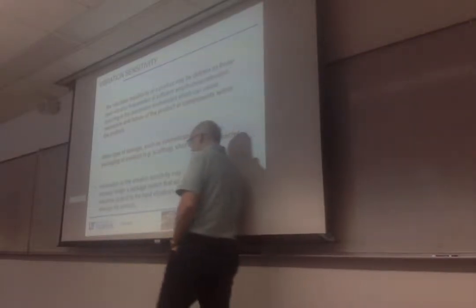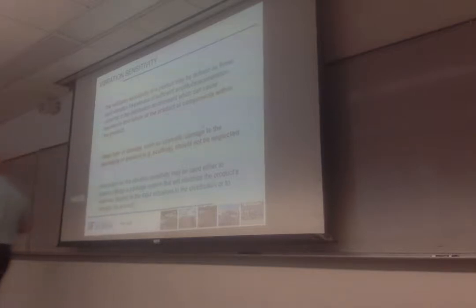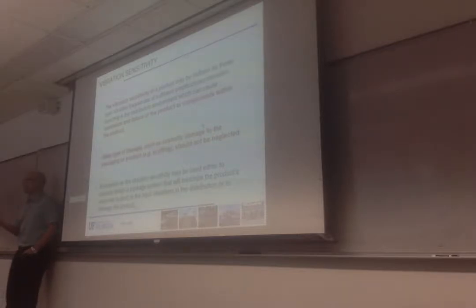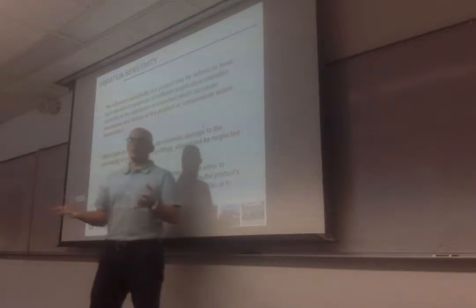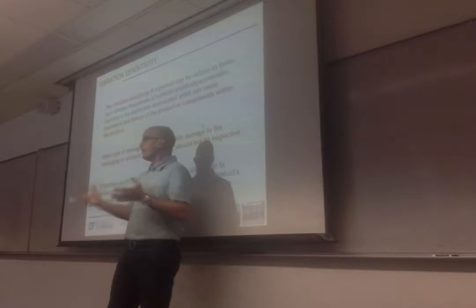One very important thing, and I think I'm going to assign this lecture a little bit later to you: if you have issues or damage in distribution and you're trying to find the cause, is it a drop, is it impact, is it vibration, remember that if you have issues with vibration, that issue should be almost systematic, particularly if you're dealing with road transportation, where your package goes on the road all the time and will be exposed to vibration.